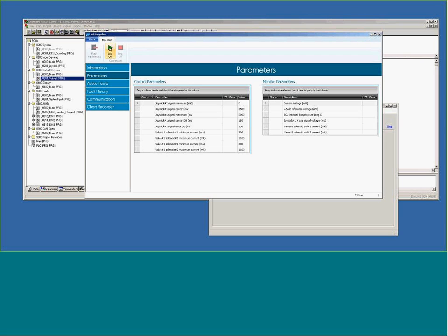So I can come over here and I can log on. We see the one line right now. If I had any errors, it would be in the lower left-hand corner. But it's okay. My ECU is showing a value of 500 and 4500, but the value of this ICF file is just showing 0 and 500. So I'm going to change these to 500 and 4500. Then I can match those values to the controller.